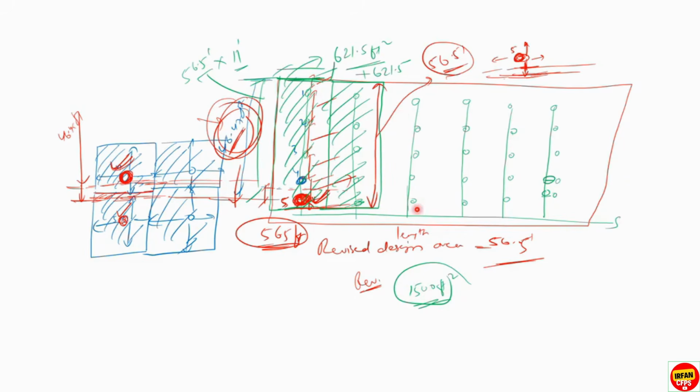So which sprinklers do you need to consider? You have to consider the sprinklers nearest to the cross main, I told you, right? So here, irrespective of the number of sprinklers, now we are going by the design area. Based on the length and design area, we calculate the number of sprinklers. In previous cases, when the sprinklers are distributed uniformly, you consider the length of the design area and the number of sprinklers, and then you define the design area.